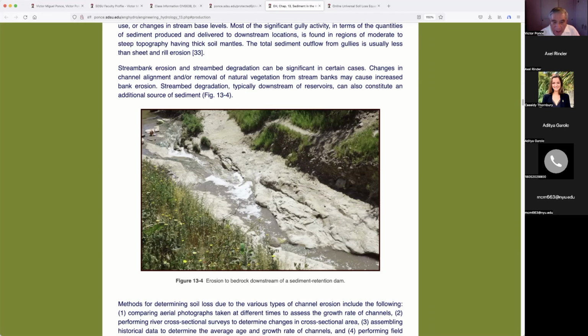But then the issue was that there were still people thinking that there's still going to be a lot of sediment. So the geotech, the main designer of the dam, came up with the idea to build a few more dams upstream, little dams, like 10 feet, 20 feet, to hold on to more sediment. And he said that it was not going to be too difficult because they were small dams. So we met to decide whether this was appropriate. And I said, I don't think so, because of the Lane relationship.